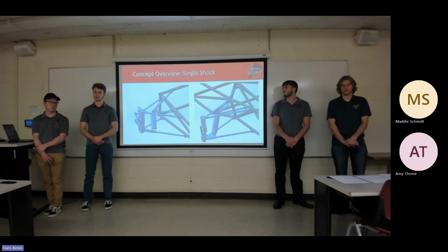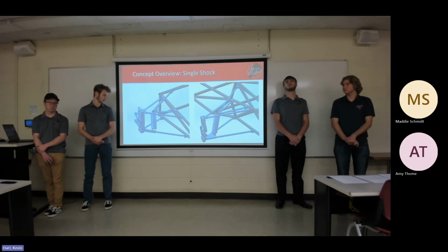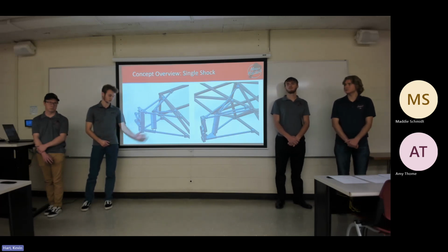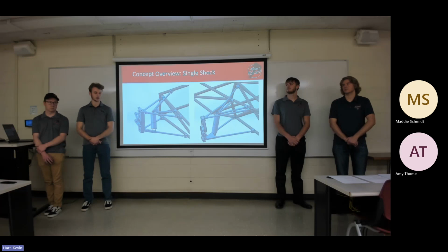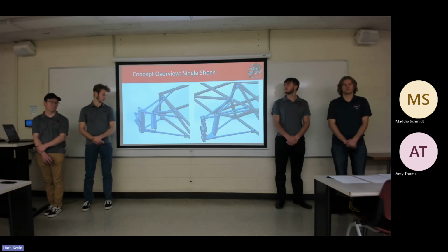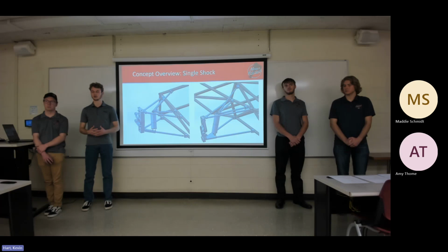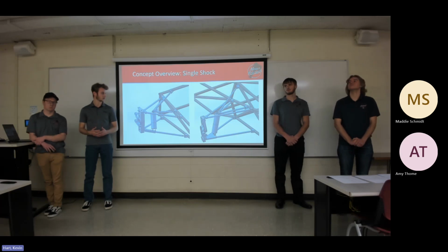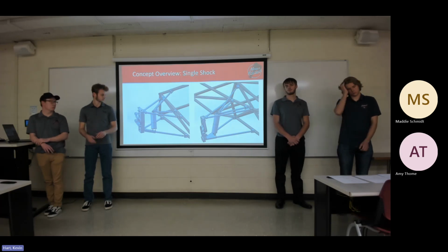And also, if the motion ratio were to be changed as the shock gets moved farther in towards the chassis, that puts a lot more bending on the control arm itself, where the mounting point would be. Otherwise, the packaging would be good, as it keeps the suspension outward of the chassis, away from other component structures.